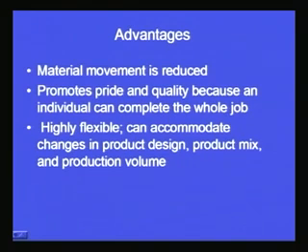It is highly flexible and can accommodate changes in product design, product mix and production volume. Flexibility is one of the most important points here. Whenever the product design changes, not much change is required. Similarly, whenever the product mix changes, for instance, instead of making a big ship we want to make a small ship with certain other design guidelines, it is very simple to accommodate in this type of layout. Moreover, when the volume changes, again it does not have too much influence on the fixed position type of layout. So these are some of the salient advantages of fixed position layout.